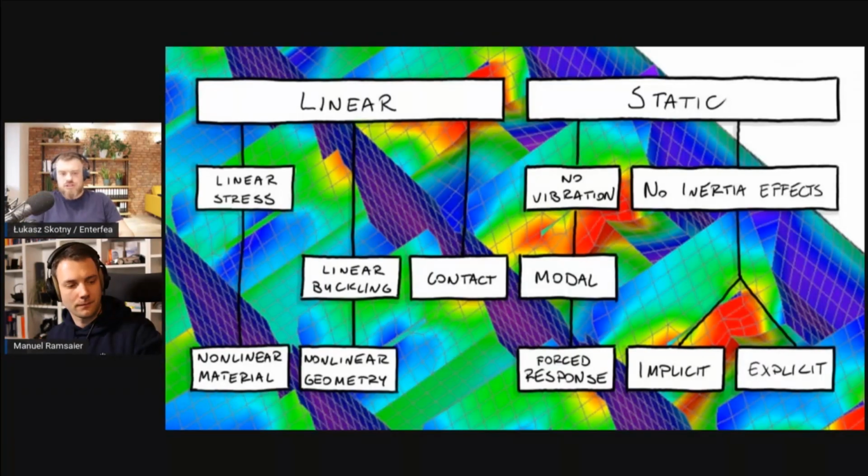So nonlinear geometry is the thing that makes a string work. If you tie a string on two hooks at two ends, and you put something on it, and you calculate it as a beam, the bending would destroy the string. It just elongates like crazy by deflecting downward. This elongation causes tension, and this is how it stays in place.